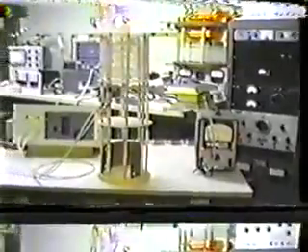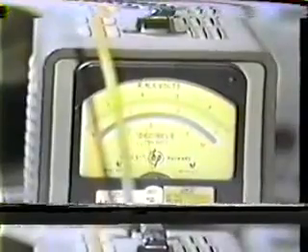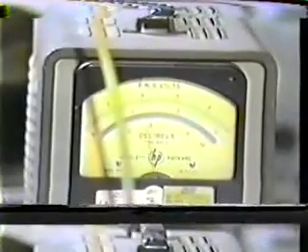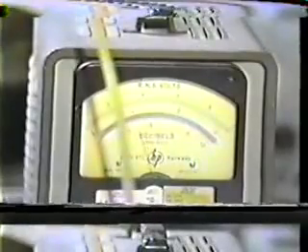to our same voltmeter. So what we'll do is we'll sweep around with the oscillator again and find out what kind of resonance characteristic we have here. Now we notice a difference right away. The resonance of this type of wave is much sharper. Rather than varying over several hundred kilocycles, now I'm varying over several kilocycles. So we're talking about a sharpness factor, or a Q, of 100 times greater.